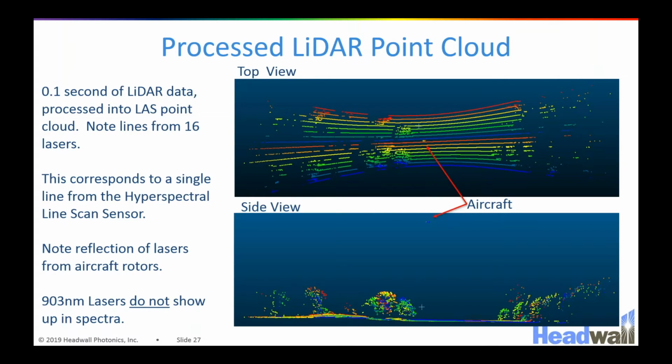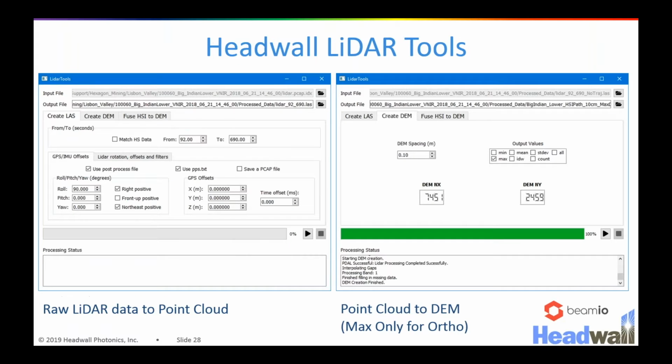Okay, so one of the key advantages in terms of hyperspectral data is that, and again, I apologize for not getting into this, but I don't want the talk to go for 3 hours. So I'm not going to dive deep into orthorectification, but part of the data processing procedure of this hyperspectral data is to orthorectify it, which will help to get out a bunch of the detection anomalies that happen as you're line scanning and your system is on a drone and it's kind of moving back and forth.